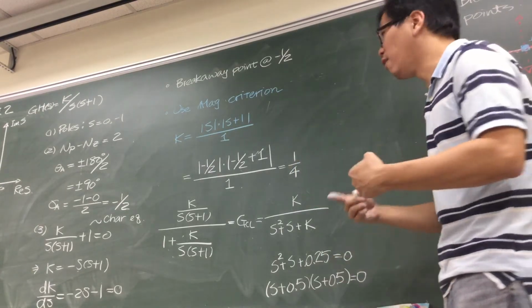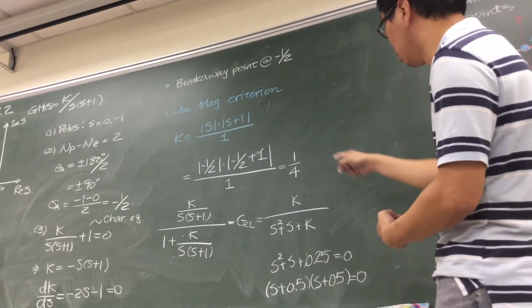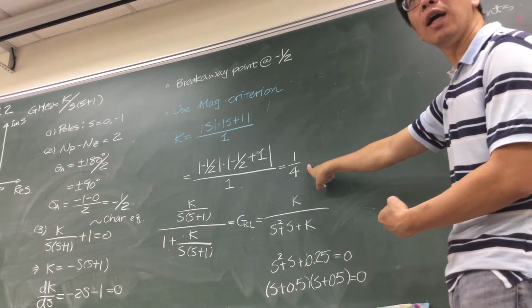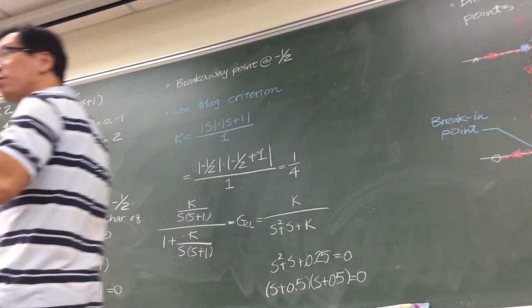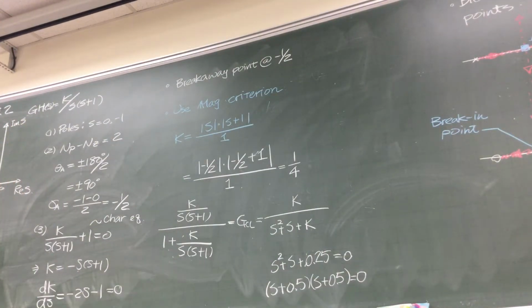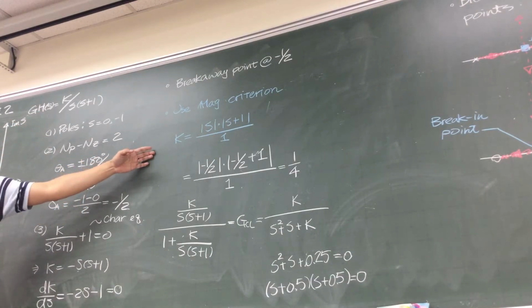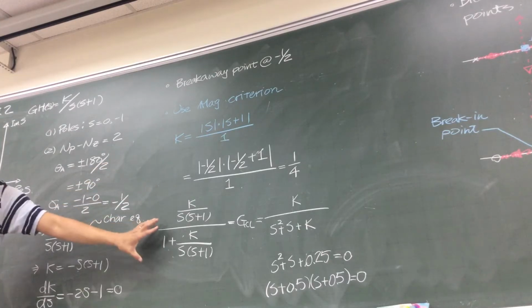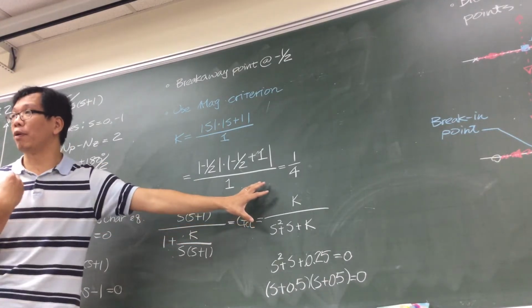Which means if I have my k equals to 0.25, I'm going to have two poles located at the same position when I close loop my transfer function, which is going to be over here. So you can use those kind of things to verify where your k is going to be located. Either use the formula, angle criterion, or you just calculate everything point by point.